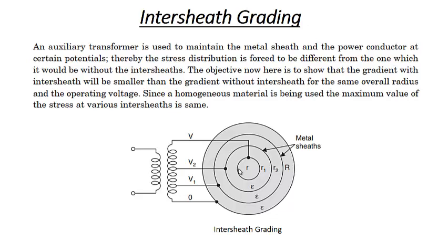In this lecture, we'll be continuing with the grading of cables. So, in the previous class, we have discussed one of the methods of grading the cables. Today, we'll discuss the second method, that is the intersheath grading. What we do in this case is use the same homogeneous material, made out of the same material, so having the same permittivity, dielectric constant, and same dielectric stress.